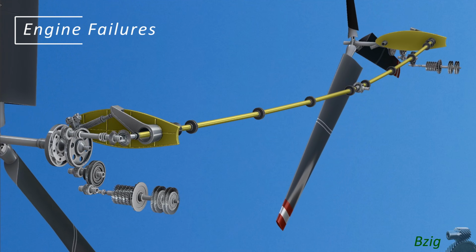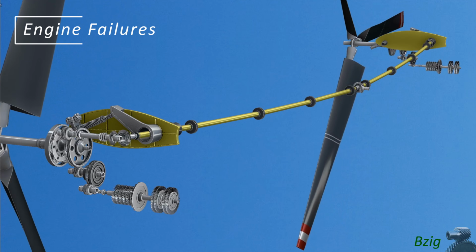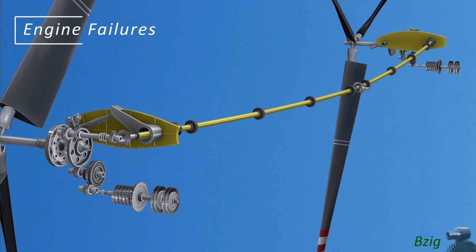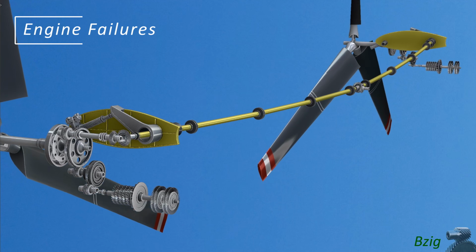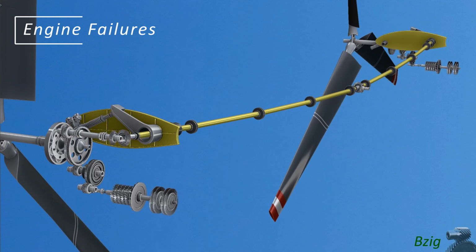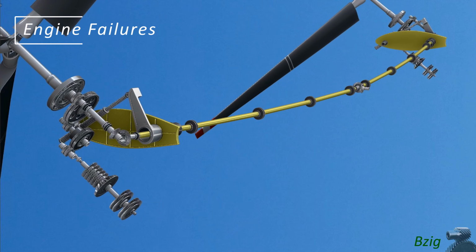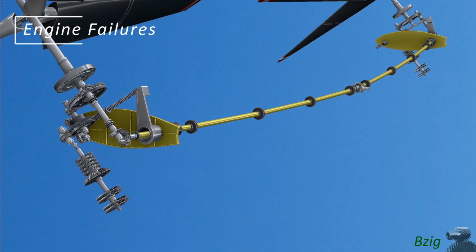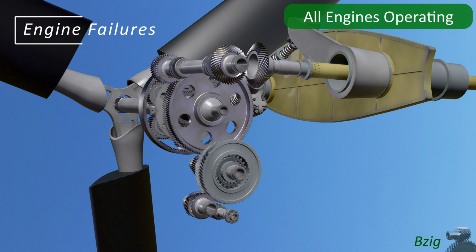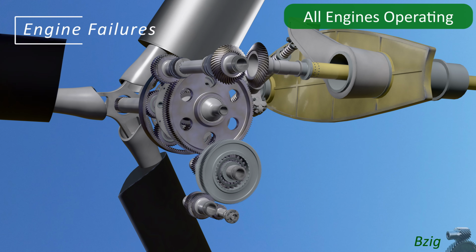In the case shown on the screen, the left-hand engine has failed and the right-hand engine continues to provide power, not only to the right-hand prop rotors, but also across the wing drive shaft, through the tilt axis gearbox, then via the Pylon drive shaft and into the Proprotor gearbox. This satisfies the safety objective of removing the parasite power of a failed engine and also maintaining symmetric thrust on both prop rotors. I'll zoom in to show a closer view of the Proprotor gearbox, and I'll hide the engine for clarity. The aircraft on screen is in powered flight.